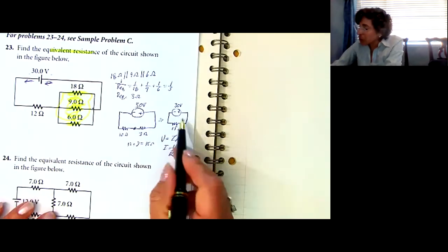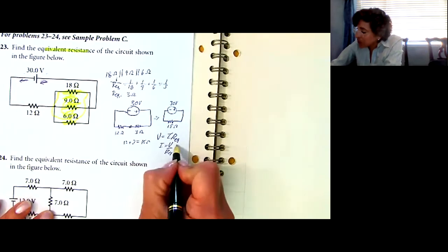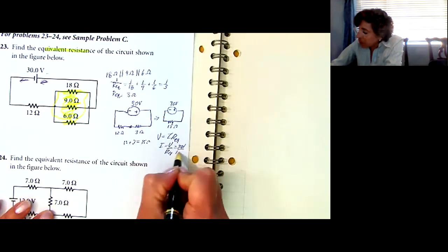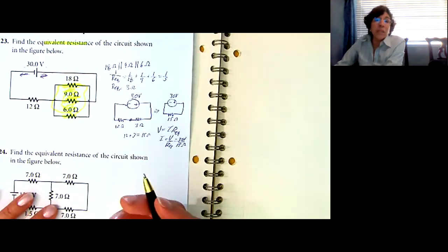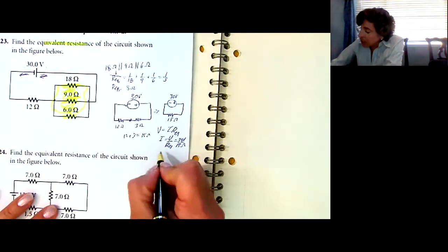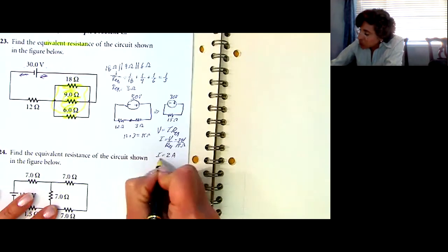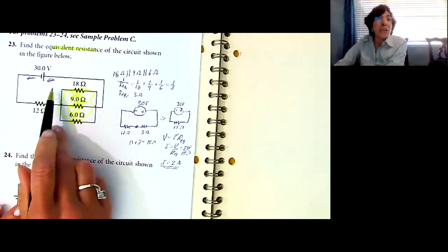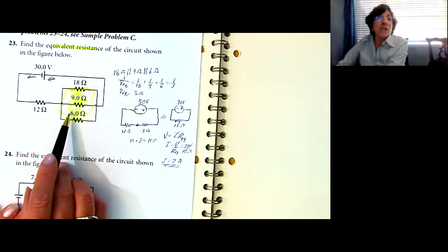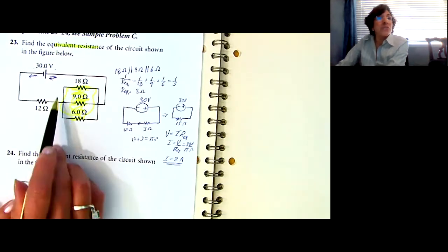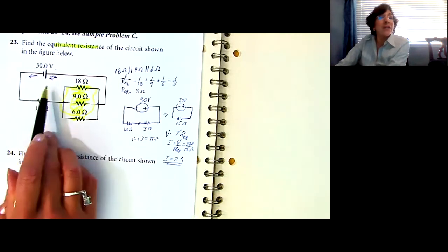So we have 30 volts and 15 ohms. And 30 15ths, 15 times 2 is 30, so I know that I is exactly 2 amps. So this battery is supplying 2 amps to the rest of the circuit. So see here going, yeah, I was right, plus minus.